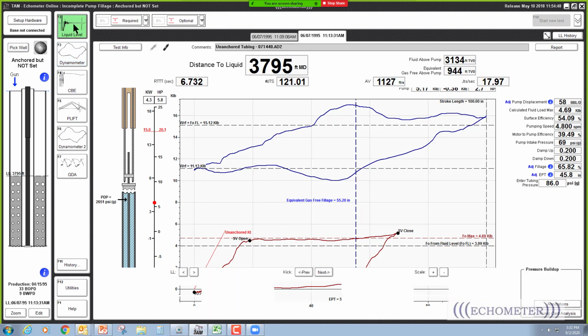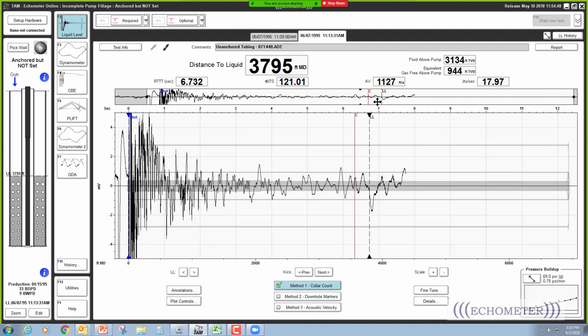If you go to the fluid level shot and look at it, this is a fairly old data set, and we probably ought to change it because this data was collected with the DOS software, and this was the liquid level that was selected by the software. The rest of the acoustic trace is cut off to save memory on the DOS computer, so you can't see that there's liquid level down here. It looks like there's a high fluid level, but there's probably not.